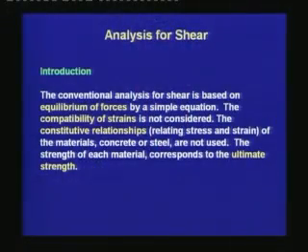The conventional analysis for shear is based on equilibrium of forces by a simple equation. The compatibility of strains is not considered. The constitutive relationships relating stress and strain of the materials, concrete or steel, are not used. The strength of each material corresponds to the ultimate strength.